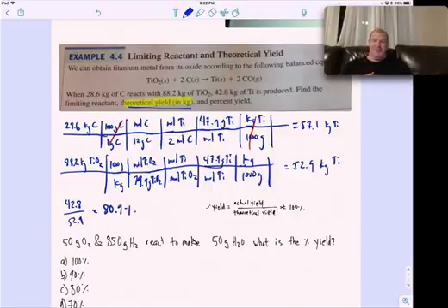This looks like a pilot plant where they were trying to figure out how much carbon, if you can actually get a little bit more titanium from the titanium dioxide, and how much more. Then it becomes a cost analysis. Let's say you get a little bit more titanium, but the carbon's more expensive. Maybe it's better not to spend the extra money on carbon and not get as much out. So that's where problems like this go.